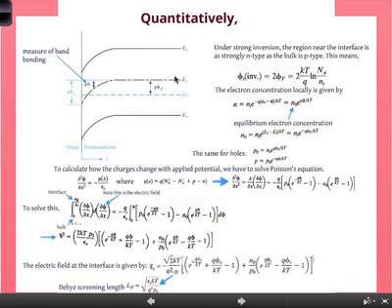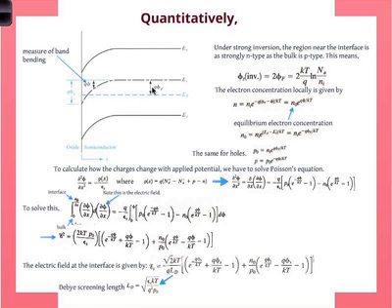In other words, what we're saying is that the band from here bends about twice as much down. And that's equal to 2kT over q times log of the acceptor concentration divided by n_i, because that is just that from there. This phi_F is determined by the hole concentration in the bulk. So that's just that.